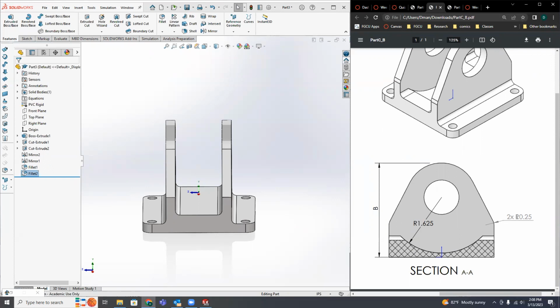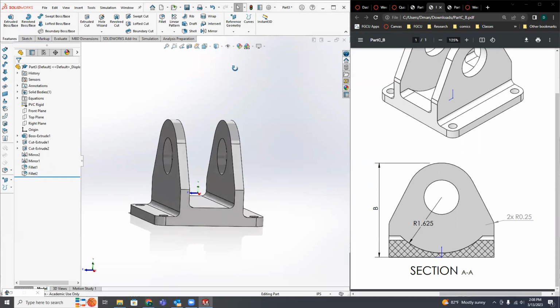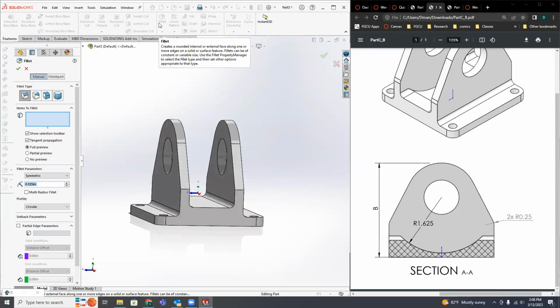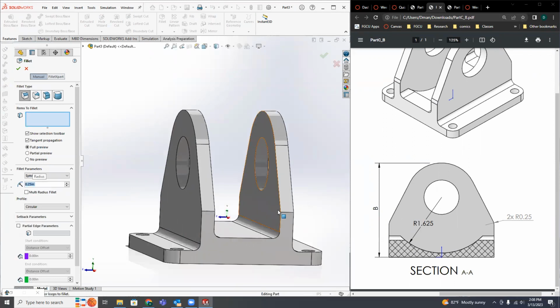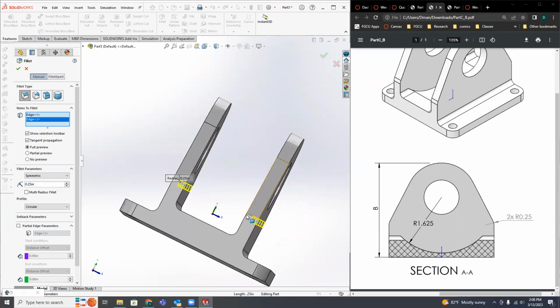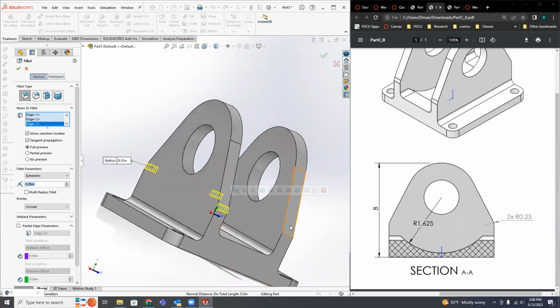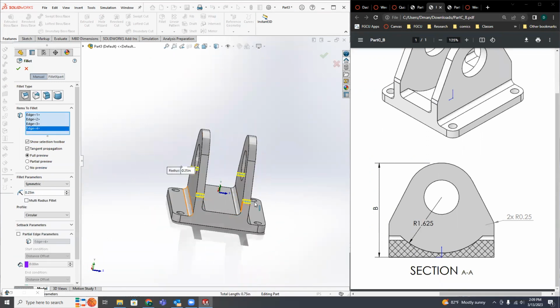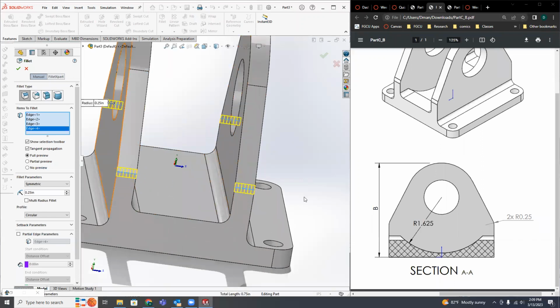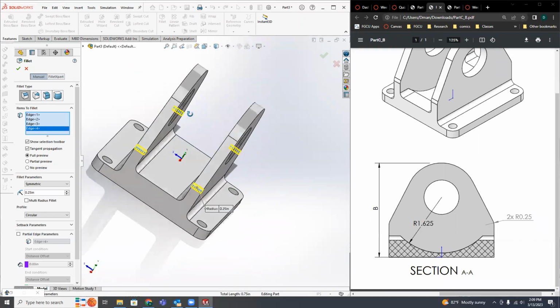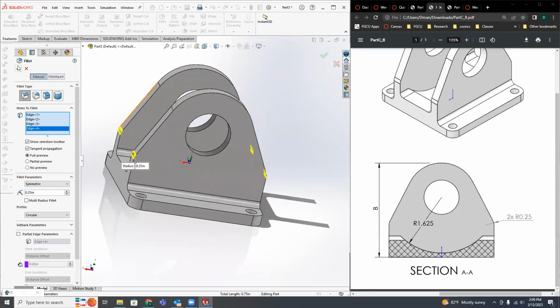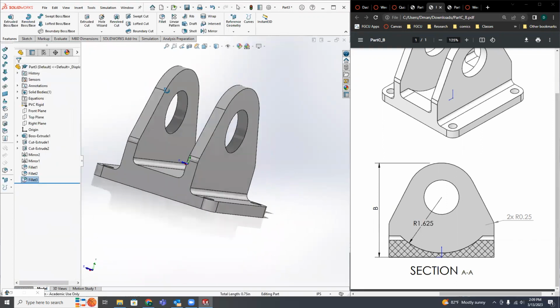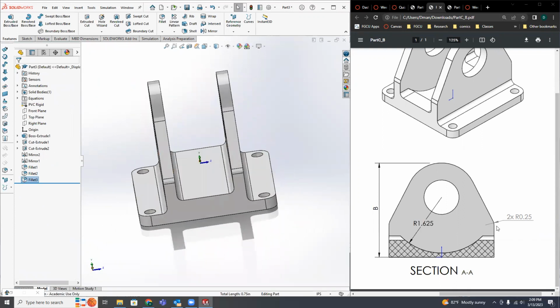We've got 2.25 rounds on the corners of this part, and you can see those here as well. So let's go ahead and do those first to finish off our fillets. So 0.25, and it's a little confusing that this is 2 because it's actually 4, but the 2 are being mirrored. It's the same edge, just projected across the cut. If you imagine these 2 lines as being one continuous edge before the center portion is cut out, that's why it says it's 2 instead of 4. So that looks good.